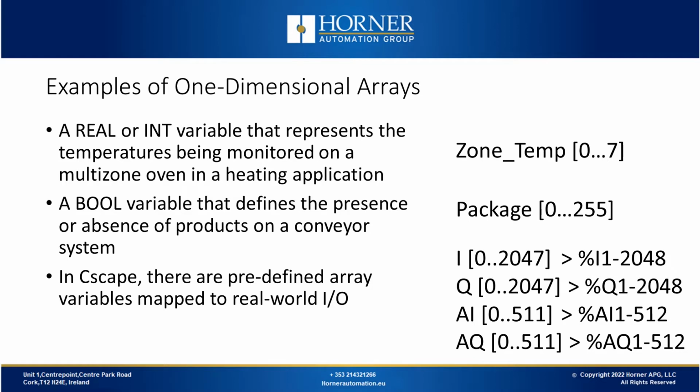Now let's talk about some arrays that are predefined in the Cscape variable-based advanced ladder. Those are located in the global variables section of the program variable window that basically map real-world I/O memory locations over to a basic array that can be used for configuring remote I/O. You can see some of those listed on the right.